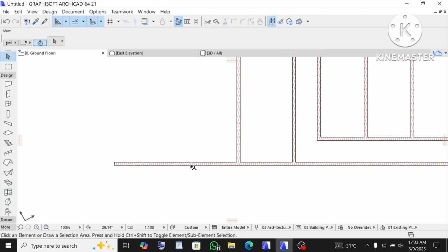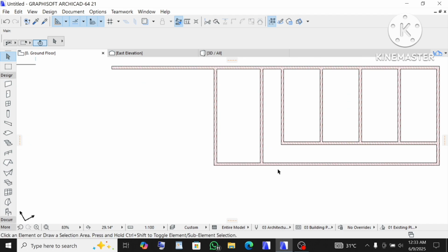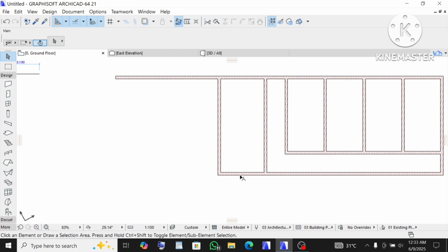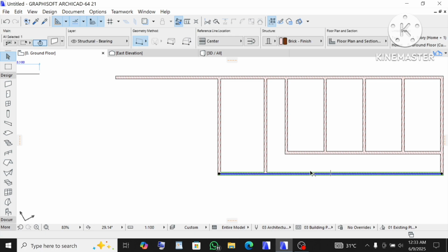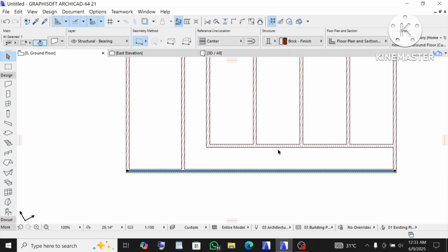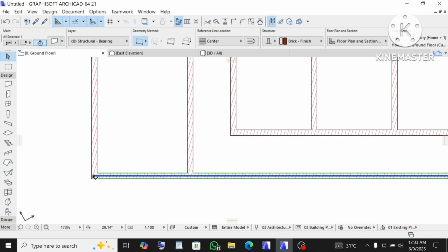Now let's remove this wall, since here is where it stops. So hold Control on your keyboard and click on this wall. Alright. Now we are going to offset this wall to the top by 4.5. So click on the wall. But as you can see, we cannot offset the entire wall. We want to offset from this part to this part.